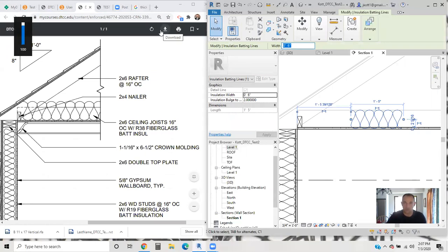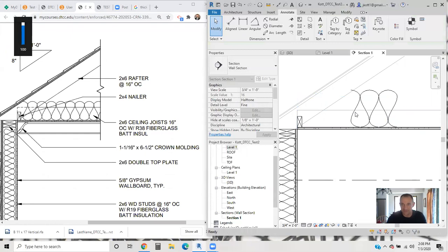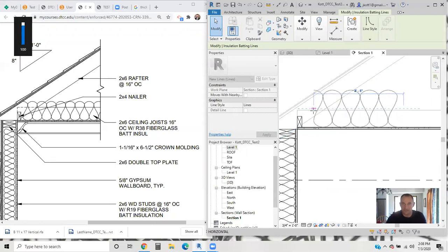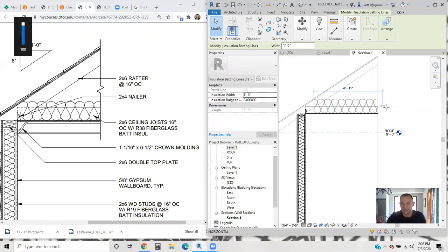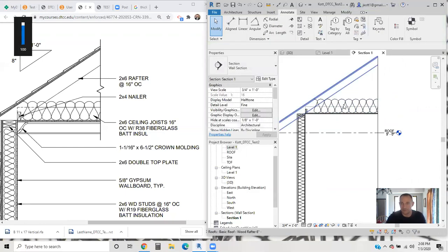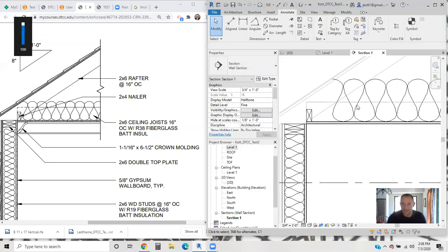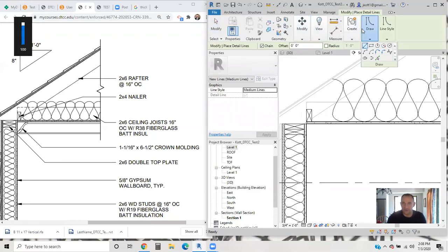We come up from 6 inches to 1 foot. And this is important. Lots of heat gets lost through the ceiling and up out of the roof of the building. So you're typically going to see more insulation in the roof to protect against that loss of heat and thermal transmittance. So now that's kind of all done, but we want to show the lines, right, for how that is hidden in the way that it is.